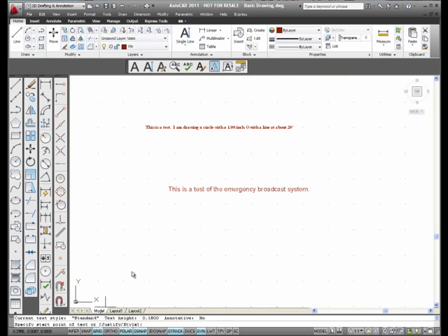It says justify, style. I'm going to type in the letter J for justify and press enter, and I want you to notice that I have align, fit, center, TL, TC, TR, ML, MC, MR, BL, BC, BR, all of this. You can figure out what align is. You can align your text in a title block. You can fit it. You can pick the center, the middle, or the right justification for a text. But this other stuff, I'm going to hit escape to cancel out of it. It is the same thing we saw when I was showing you the different types of